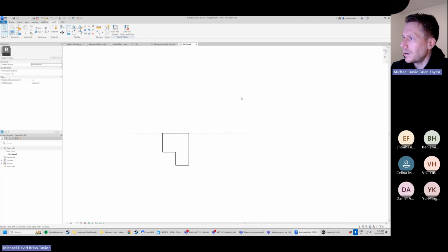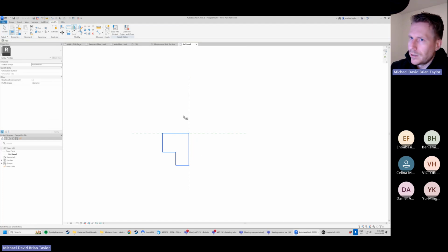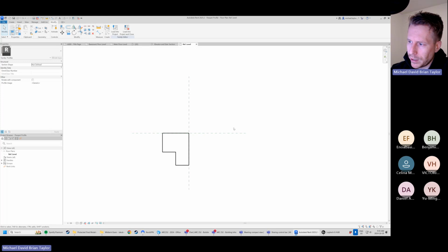Oh, he's done. Never mind. I don't have it. So he's actually had it flipped. So if you had this one, it may have looked something like this. And that was causing some issues for us. It doesn't harm the model, it just makes it a couple extra steps. So what I had gone ahead and done was I actually flipped this before I inserted it inside the Revit model, so we can have it just be in the right orientation before we get the profile in here.